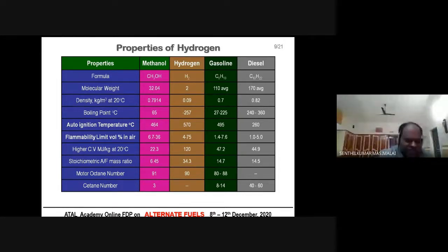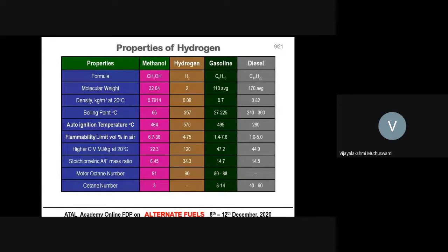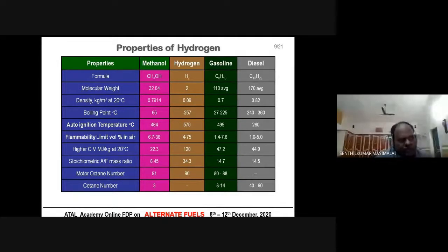Sir, some audio disturbance is coming. So, you are saying directly using mahua oil is a problem, because it is in greasy form, right? Actually, for our case, above 30 degree centigrade, we did not find any semi-solid form of mahua oil. In a cold climate, like in winter, we observed that the mahua oil is in solid form. So we heat it up to 30 degree. We are not heating up to 50 or 60. That will have some other reason. Up to 30 degree we are heating, and we are using it, no problem.